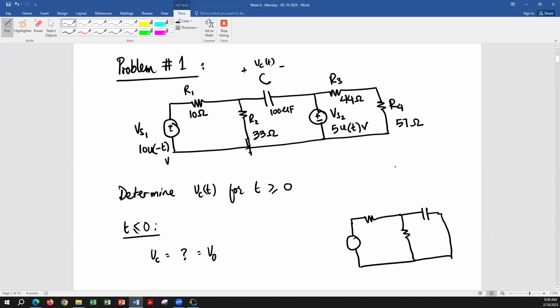All right, once I short that out, that means my R3 and R4 will be in parallel with the short. That means they're just going to be gone. There's no current that will flow through R3 and R4. Everything is going to go through the short, if there is any current going through that. And I can easily remove R3 and R4.